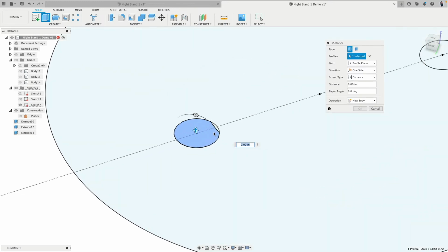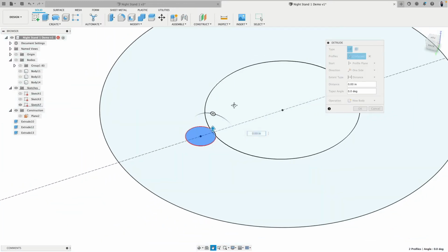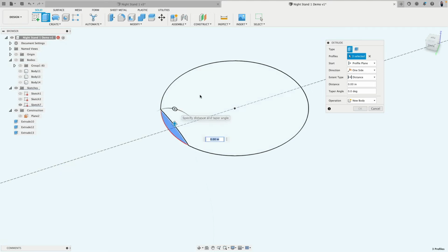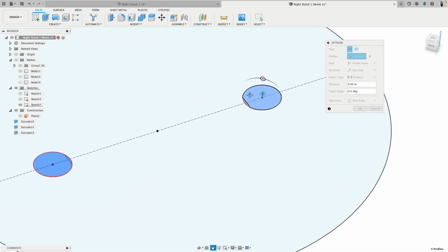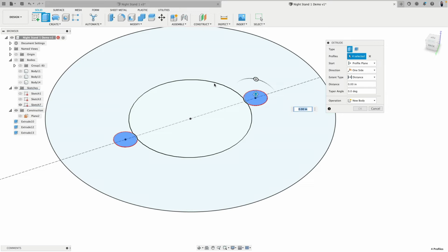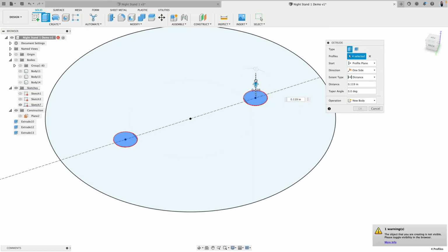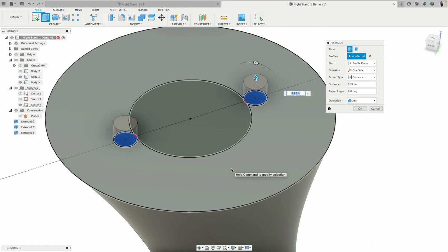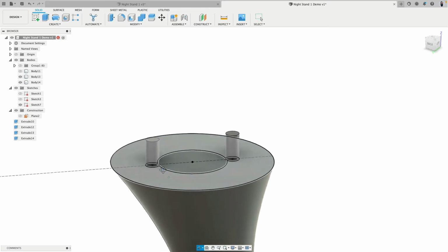Extrude. So and we have to be careful now. There might be some fragments. We don't necessarily see this really well. So it's an interface issue, but we know this is the circle from the initial loft. And now this whole thing we bring up. Question is by how much? 0.75 is the thickness of the board. 0.5. That's good. Then we have 1/4 of an inch material left.